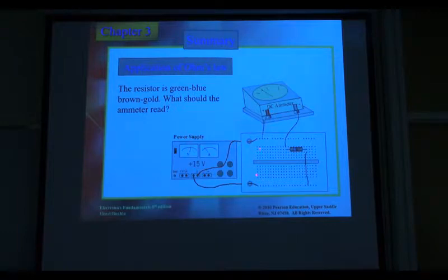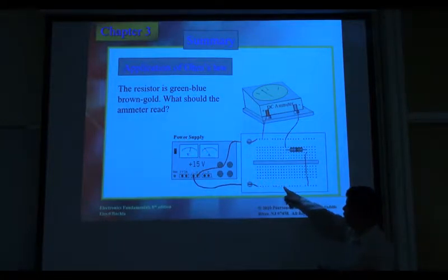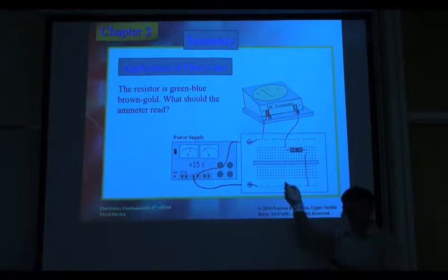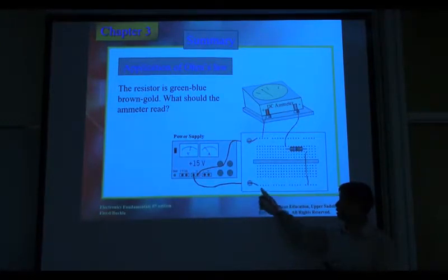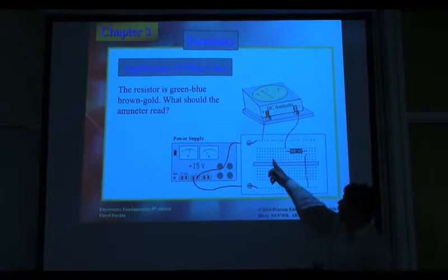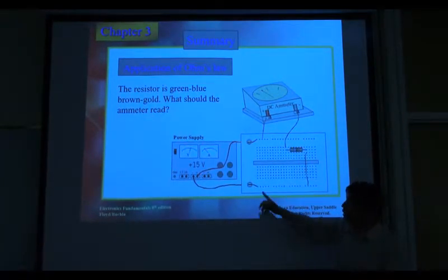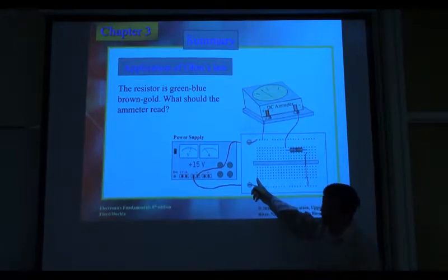This one is a breadboard. You are going to use this in the class later. Yesterday, I don't think you discussed this, but later you will. So on this board, this line are connected. You think under this hole there's only one straight line, so these are connected, and these are connected. This one you need to memorize. And all these are connected.